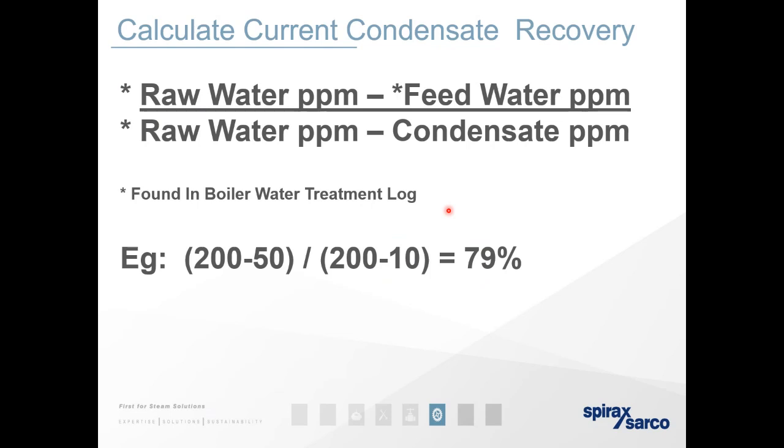So when we say flash steam, what we're talking about is you have traps which remove the condensate, as the question says. That will be under pressure. You have a differential pressure that then comes across the steam trap. So when it reaches the condensate line after the steam trap, you will have a percentage of steam which has turned from where the water has suddenly decompressed.